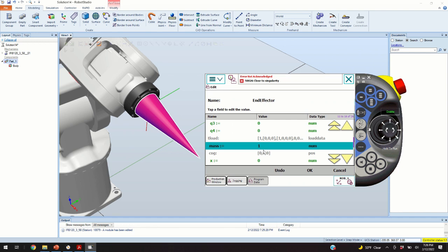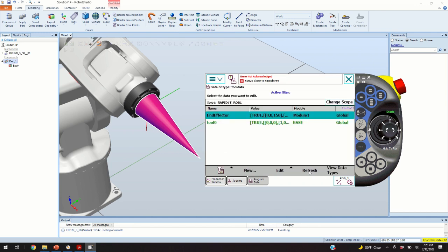Well, because by properly specifying the mass, you will make sure that the robot controller takes into account that mass when computing control voltages for the joints. Heavier mass requires more load, that is, more torque to lift. So by precisely specifying the mass, you can basically increase the optimality of your controller. And you click on OK.